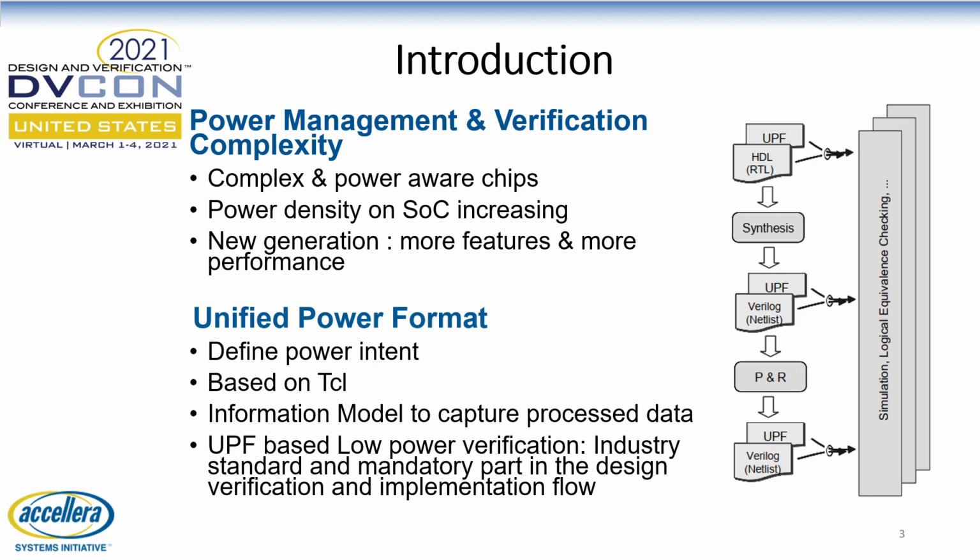UPF, Unified Power Format, accomplishes this by allowing the specification of what was traditionally physical implementation based power information early in the design process at the RTL level. It is based on a Tcl script and provides concepts and commands which are necessary to describe the power management requirement for IPs or complete SoCs. The figure beside here shows the UPF supporting the design flow from top to down.